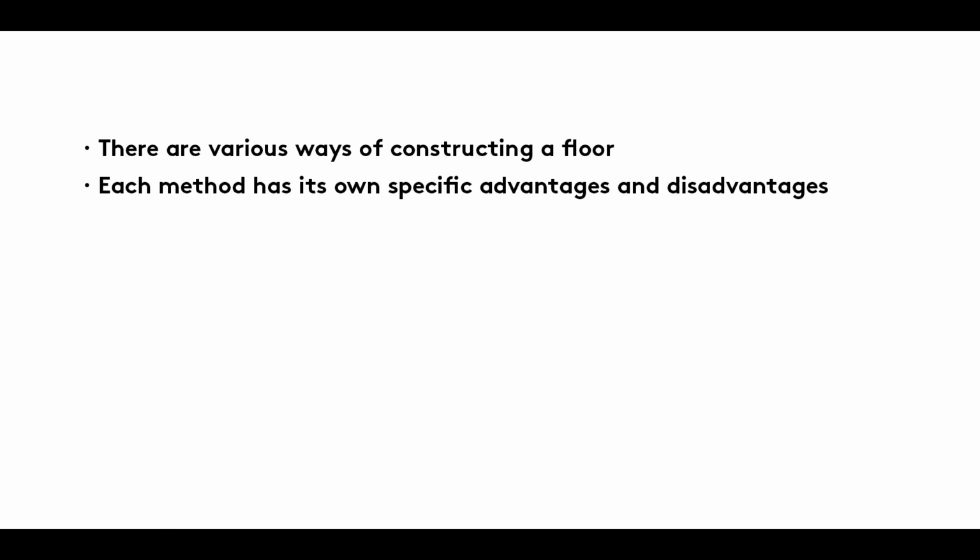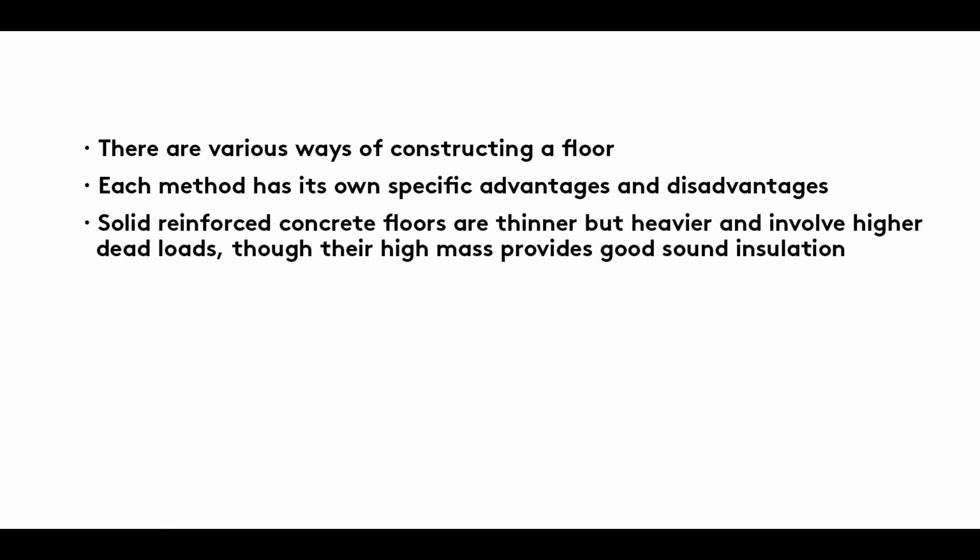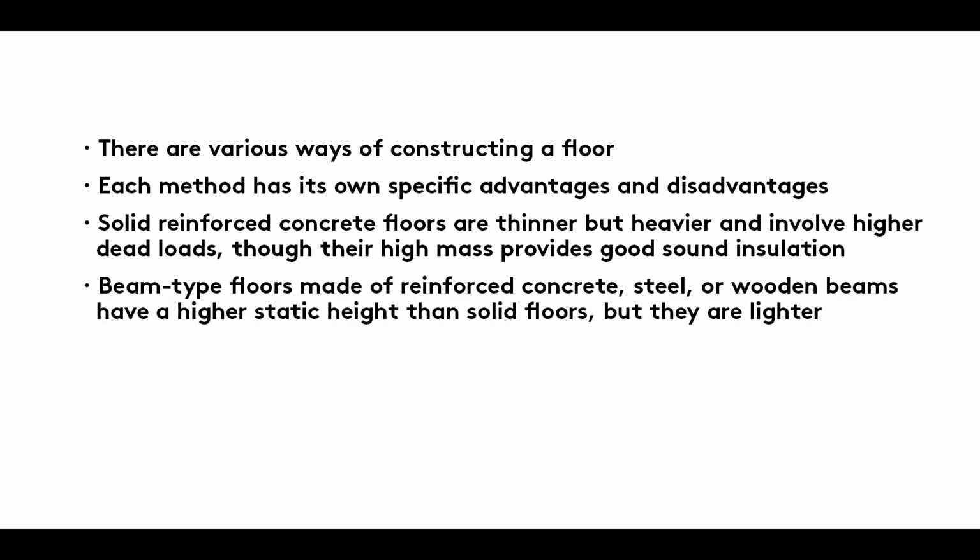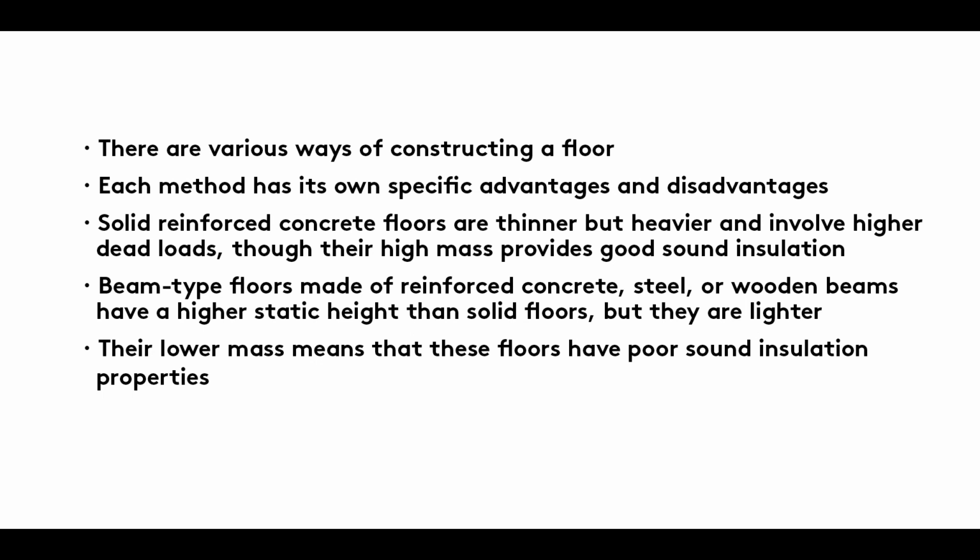Summary. There are various ways of constructing a floor. Each method has its own specific advantages and disadvantages. Solid reinforced concrete floors are thinner but heavier and involve higher dead loads, though their high mass provides good sound insulation. Beam-type floors made of reinforced concrete, steel or wooden beams have a higher static height than solid floors, but they are lighter. Their lower mass means that these floors have poor sound insulation properties.